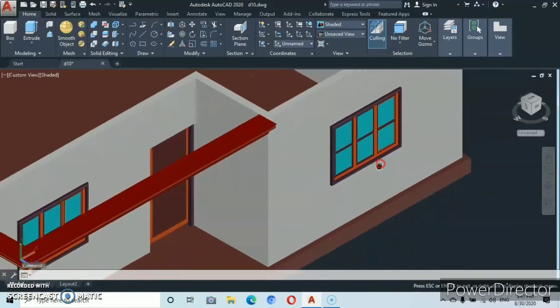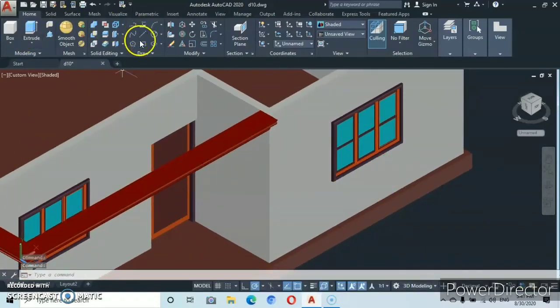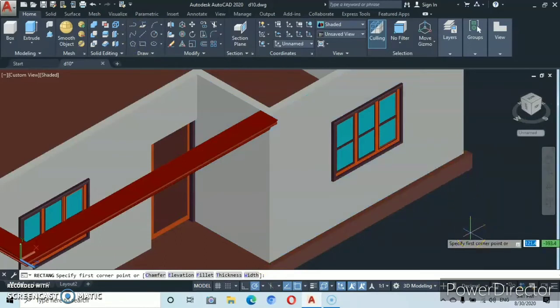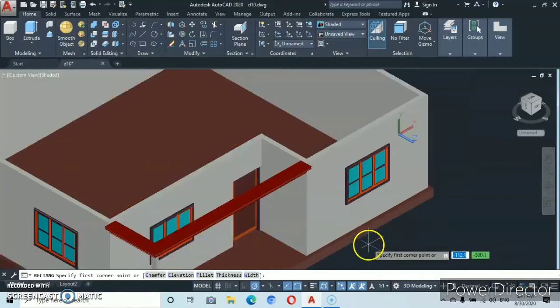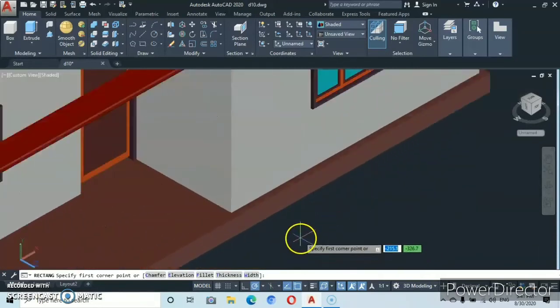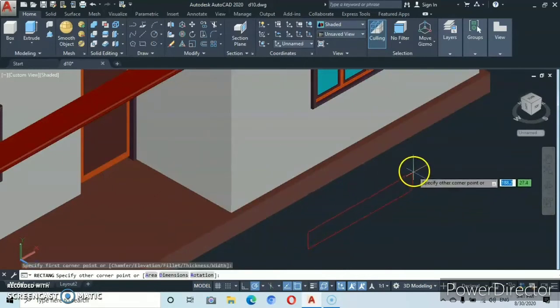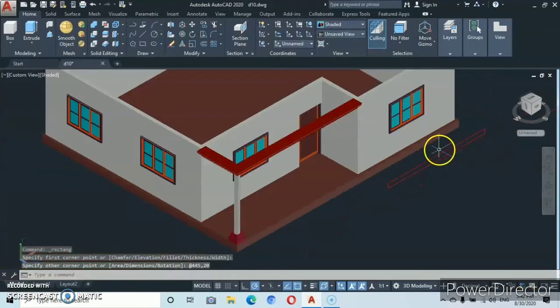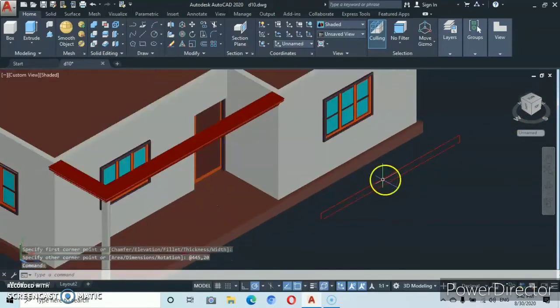And before we start it all up, let's first of all go to the rectangle, because this wall from here to here measures 445. Then so the height of our cladding is going to be 20. Okay, so remember we already set our units and we are working in centimeters. So I'd like us to come somewhere outside and click there to draw our rectangle. Let's pull it here and type in 445 comma 20. Okay, 445 by 20. Sorry for that. Enter. Now we are going to have something like this.